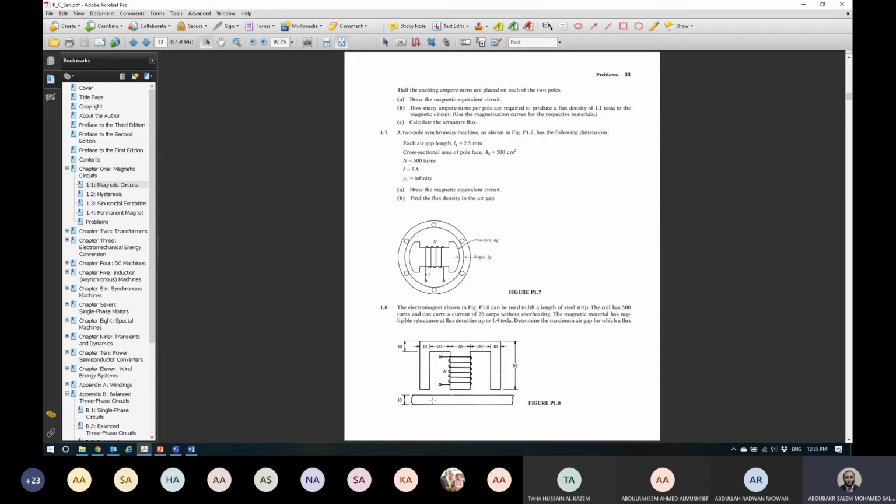So what will be the equivalent length in the lower part here? Is it going to be the overall length, or just the length that the flux is going to move here, like the upper one? Which is right, guys? And we calculate this one as 70. The upper one here, the average length is 70. So it will be like the upper one. Exactly, same. Because this will be the effective length that the flux is going to move. So don't care about all of the dimensions. We care about the dimension of the track that the flux is going to move.